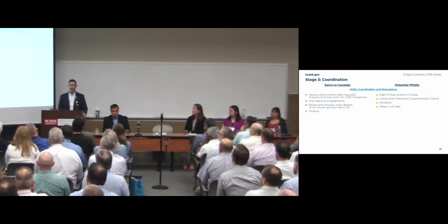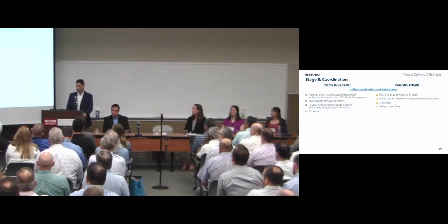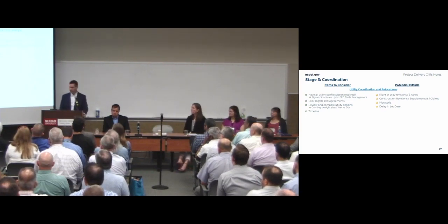Traffic management, is there a utility relocation that's going to require a deep excavation? Are we taking that into account if it's within the project duration? And is there a phase that we need to account for with a road crossing? So a lot of things to think about there.